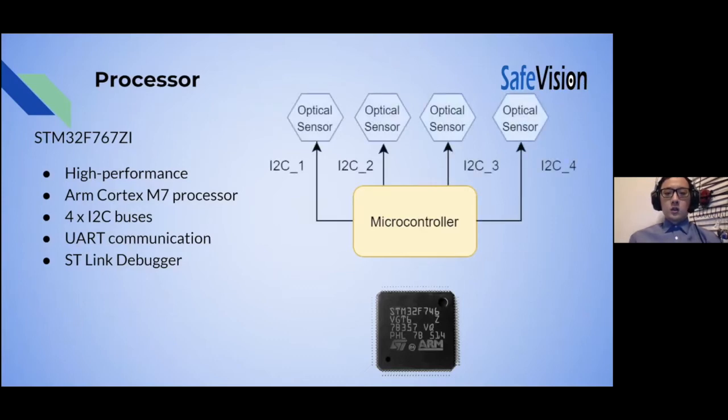As you can see here, the microcontroller has 4 different I2C buses that help us separate out the sensors. We'll talk more about this later, but the sensors that we're using are in breakout board form, so the pull-up resistors are still attached. The independent I2C buses prevent them from being combined together, which would produce a lower pull-up resistance for each bus that can result in overdrawing current through the devices and overheating.